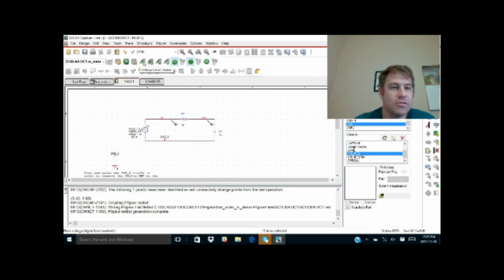So this is a voltage level marker, this is a voltage differential marker. Now I can actually put a current marker. So why don't I put a current marker entering this node of the resistance? I don't really need to put one here because it's going to be the same value, obviously. Okay, so let's simulate this now.